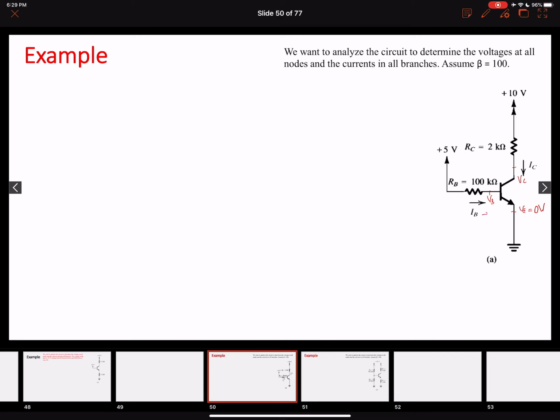And we know that the value over here is VBE equals 0.7 volts. So again, we are starting from exactly the same assumption. Our emitter to base junction is forward biased. It is 0.7 volts. Since the emitter terminal is grounded, our base is at 0.7 volts. Okay, so if our base is at 0.7 volts, if I know the value of this VB over here, I can easily solve for this to find out the base current.